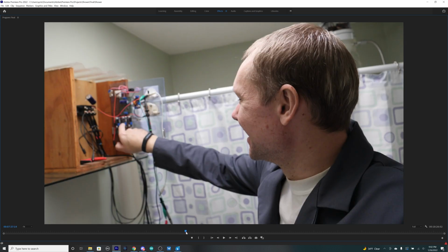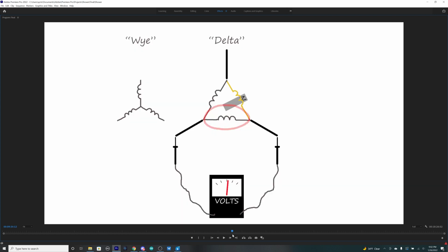Let's get to our three-phase stuff. Three-phase power is what industry runs on. You look at the hydroelectric dams, nuclear, coal-fired, whatever it is, they're all spinning some sort of generator that has 3 phases built into it, and it's way more efficient that way. It runs smoother, it's all good. But homes don't typically have 3-phase, and I've been shopping for lathes, trying to see if I want to upgrade my single-phase lathe, and you'll find one at a good price and you realize, oh, that's a 3-phase machine. I'm not going to be able to run that at my house without some sort of phase converter.